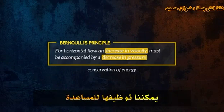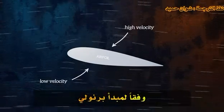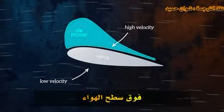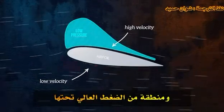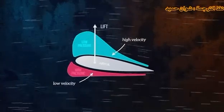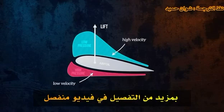We can use it to help explain how plane wings generate lift. Fluid flowing over an airfoil travels faster than fluid flowing below it. According to Bernoulli's principle, this creates an area of low pressure above the airfoil and an area of high pressure below it. And it's this pressure difference that generates lift. I'll cover lift and drag forces in more detail in a separate video.